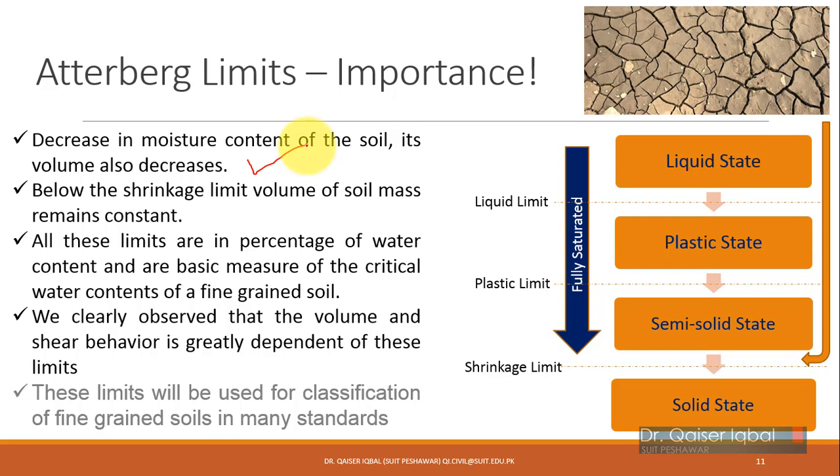In many cases you have seen that you place some mortar or some soil with very high moisture content, and when it becomes dry, it develops cracks, because with reducing moisture, the volume has reduced as well, since it was in liquid state while you were placing. Even in case of cement, if you put too much water in it and place it like a slurry, you will see when it dries, it will develop cracks. So it is very important to know that if you are placing a soil in liquid limit, it will change its volume a lot upon drying.